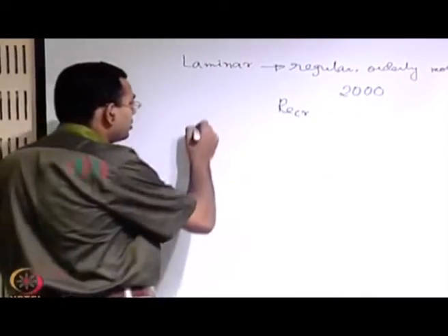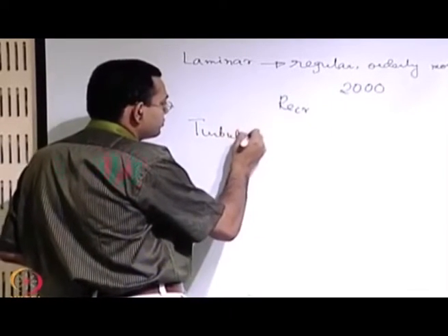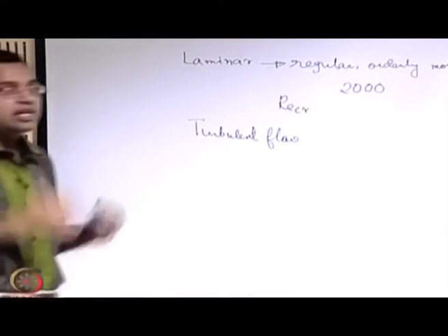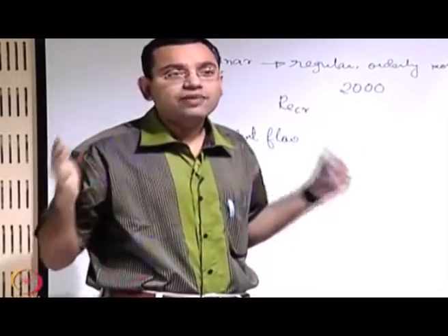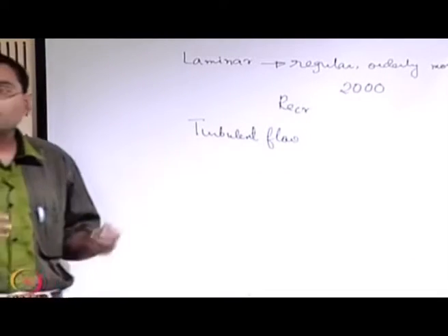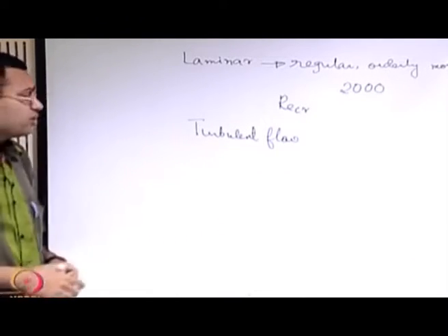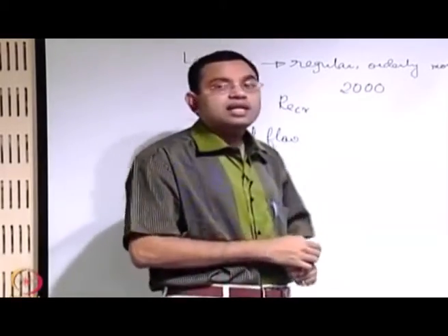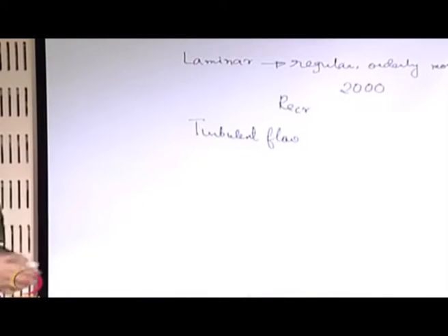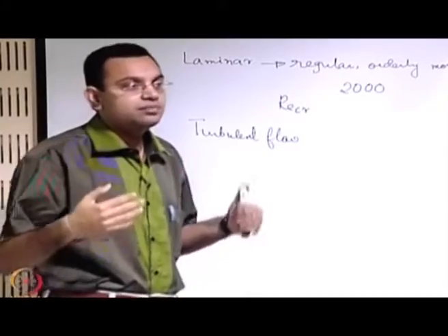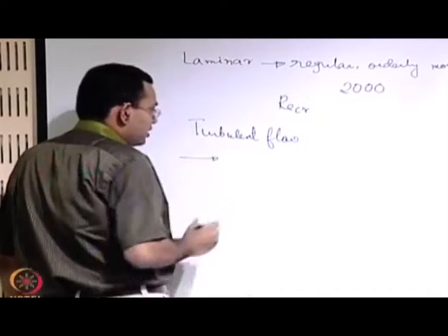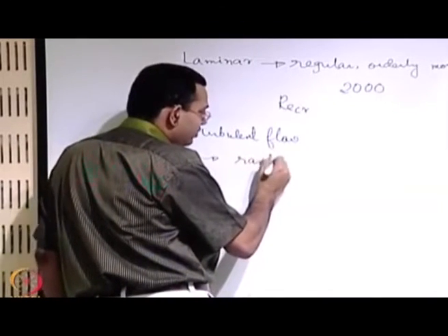Whereas when you are talking about a turbulent flow, it is not so easy to have a single formal definition of turbulent flow, and we will not try for that. We will go for a qualitative physical feel of the turbulent flow with its important characteristics. So let us identify some of the important characteristics of the turbulent flow. One of the characteristics we could identify by visualizing this apparently simple but very thought-provoking and interesting experiment is that there is a randomness of the velocity.